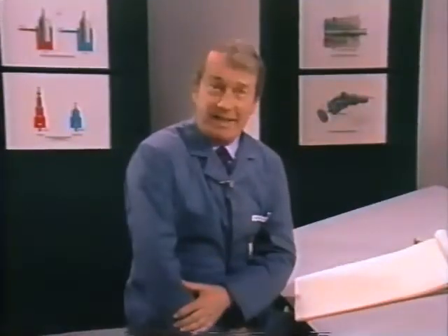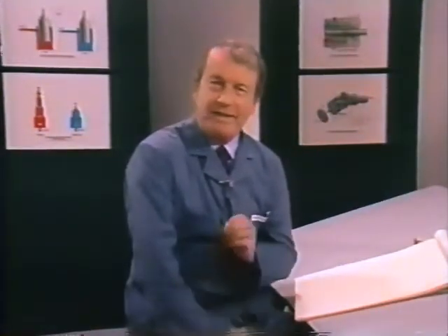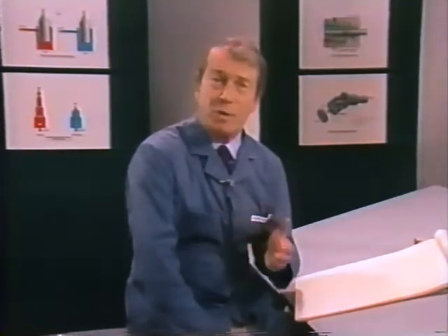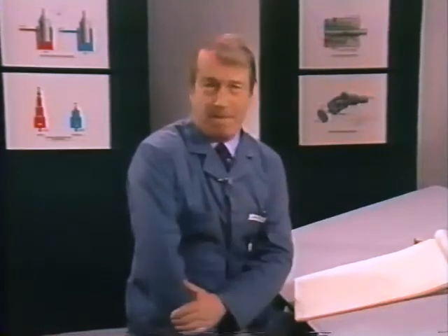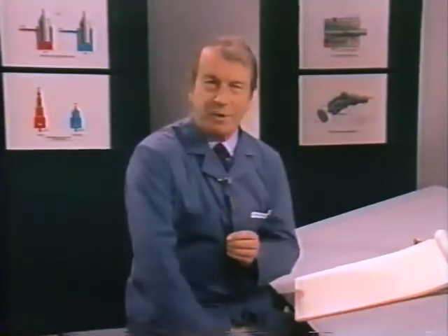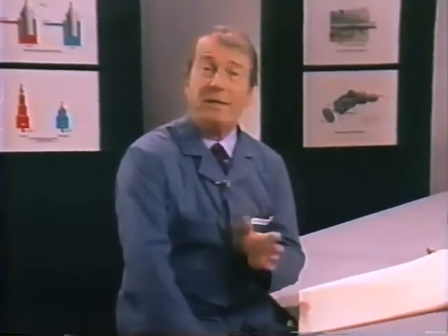Now then, let's analyze terminology for a moment. In dealing with linear motion, we talked in terms of so many pounds of force required for a cylinder to move a load. With rotary motion, we talked in terms of torque. The definition of torque is simply force times the radius arm. Torque ratings of hydraulic motors, whether they be vane, gear, or piston, are usually given in so many pound-inches of torque per 100 psi of operating pressure. With very large motors, it's usually expressed in pound-feet of torque.